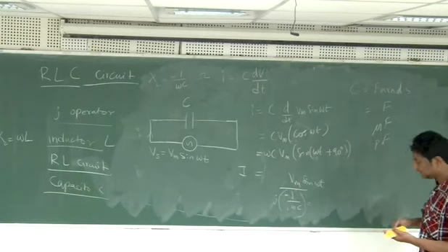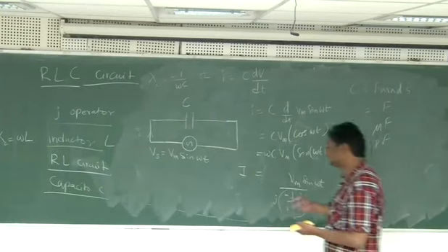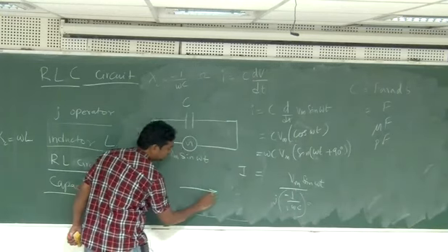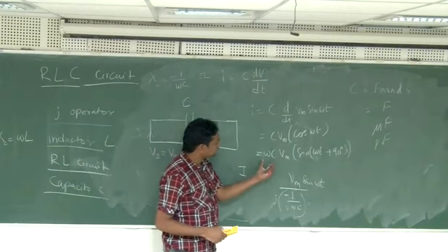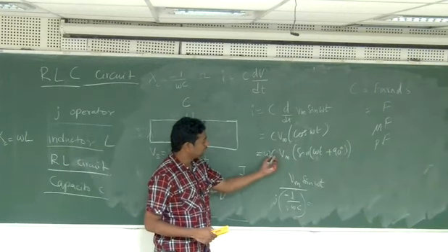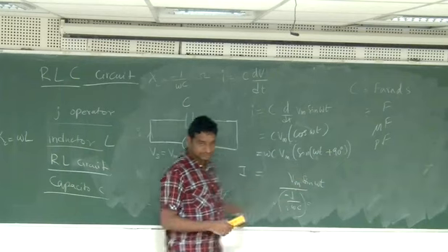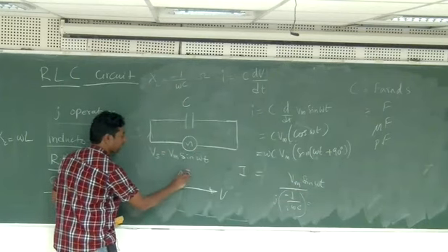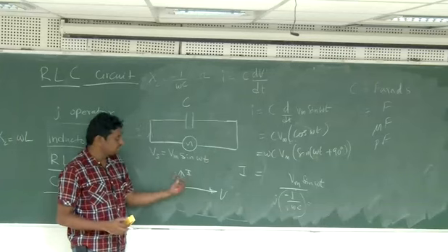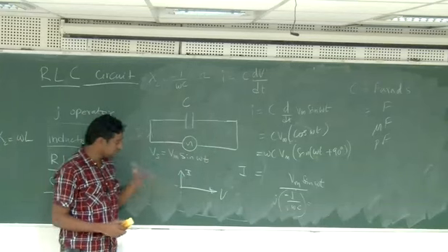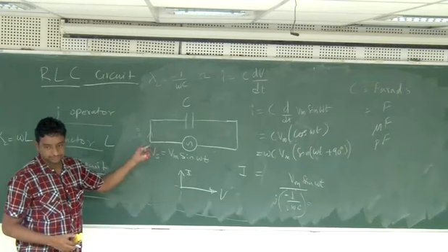So what about the vector diagram or phasor diagram? If this is V, you can notice the current is some quantity multiplied by 90 degrees plus. So it will be like this. V into j is I, and the length will be different based on the value of C.